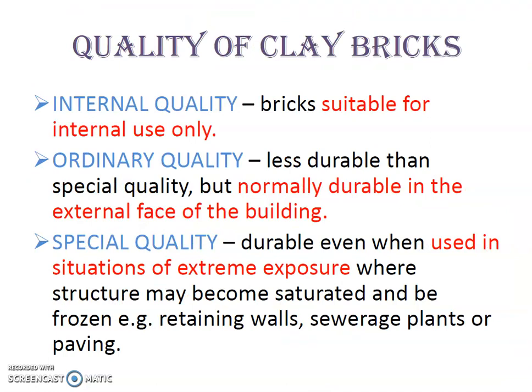Clay bricks are divided into three categories of quality, which are internal, ordinary, and special. Internal quality determines that the bricks are suitable for internal use only. Ordinary quality means the clay bricks are less durable than special quality, but are normally durable in the external face of the building.